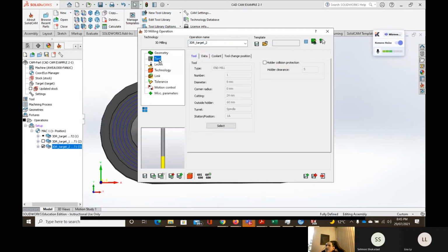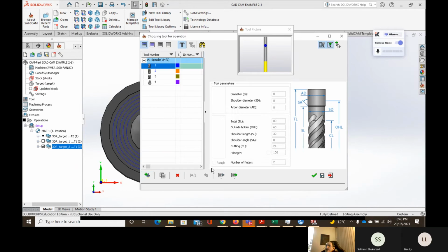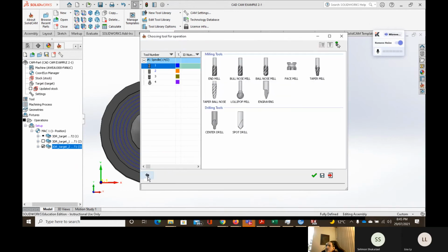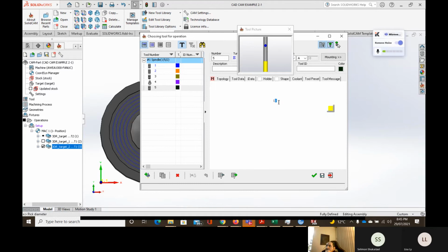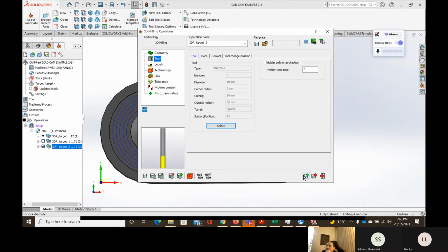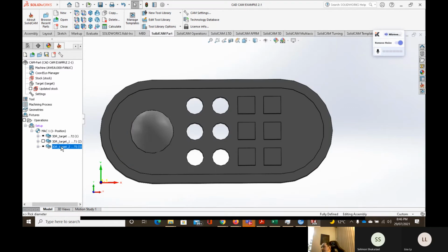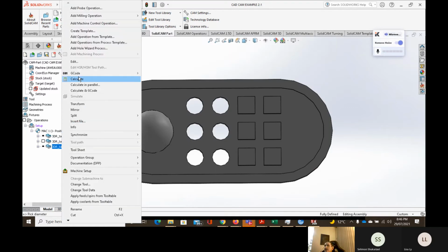Just let me give something. So for the tool, select again, to add another tool that is going to have 10mm diameter, 10, because that's actually the actual distance we have, 10. I hope it will work. I remember that once it hadn't worked. Okay, so save and exit. Let's see if it's going to work.